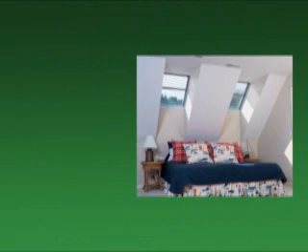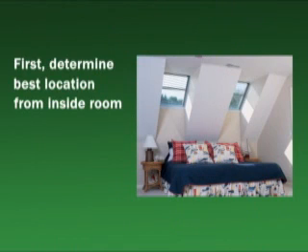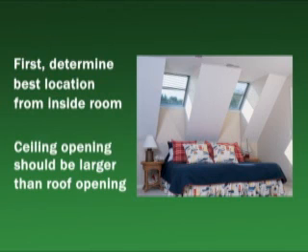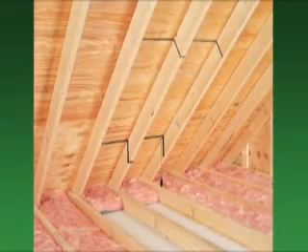Based on the size of your roof window or skylight, first determine the best location to open your ceiling from inside the room. The ceiling opening should be larger than the roof opening to provide the best light distribution. Now get ready to prepare and cut the roof opening.